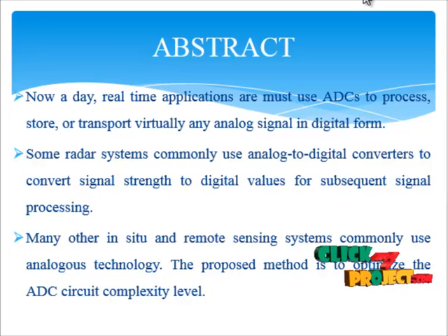The ADC has been fabricated in the 180 nm CMOS process, and we implemented the ADC with an improved SHA, optimizing the bootstrap switches to achieve high sampling linearity over the input frequency range.